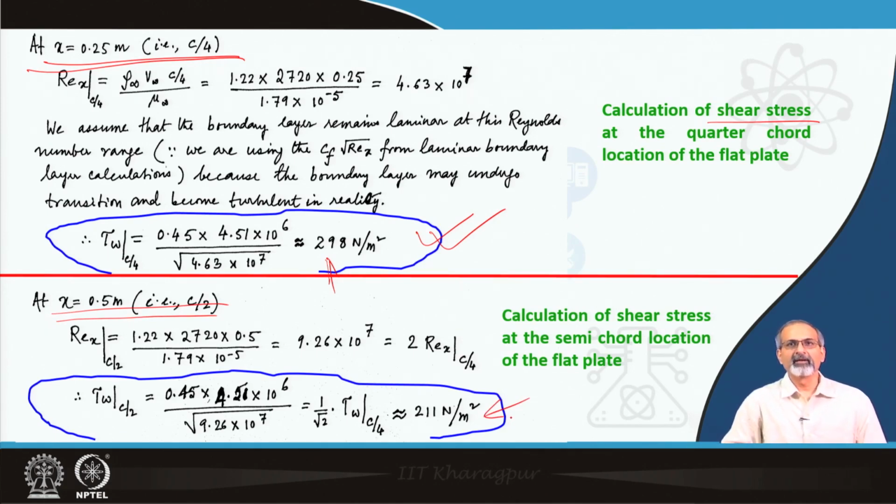Also remember, based on the basics of boundary layer theory, that closer to the leading edge, the shear stress is always larger. The shear stress spikes close to the leading edge, and then it decays rapidly as you move towards the later part of the plate, because of the rise in the boundary layer thickness, since it is dependent on the gradient of velocity.